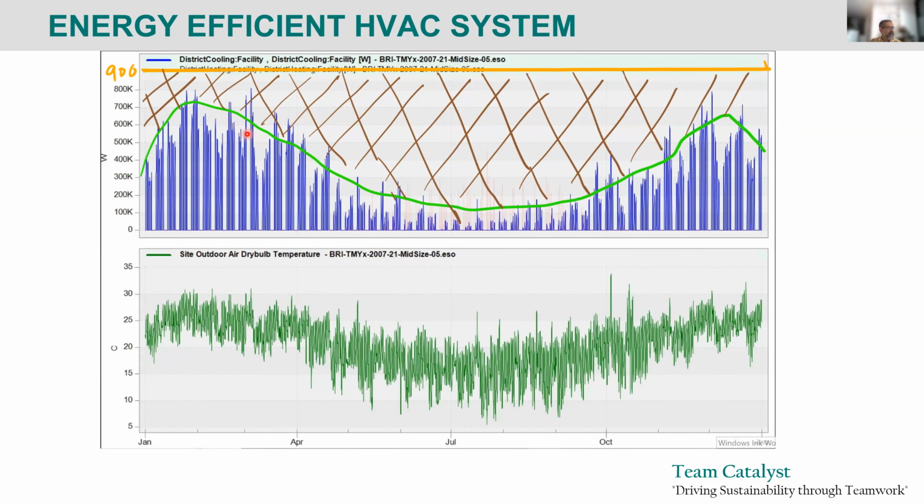Now, this is what the simulation predicts as hourly loads. When air conditioning engineers do sizing, usually we're looking at a much bigger system because there's a couple of safety factors. You're using quite an extreme weather condition, etc., to do the sizing.